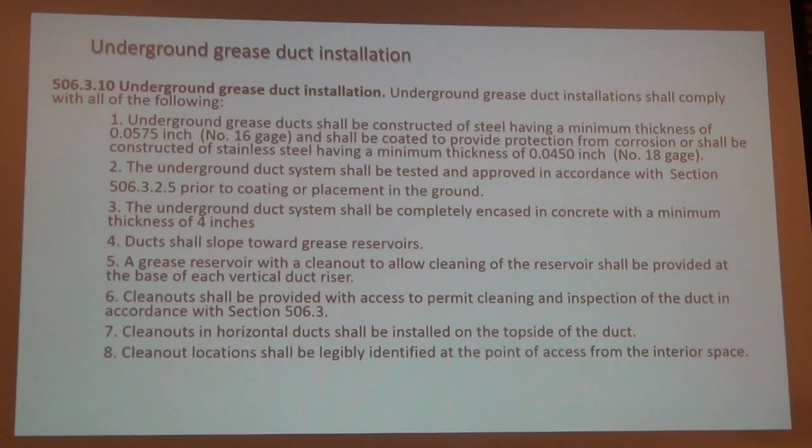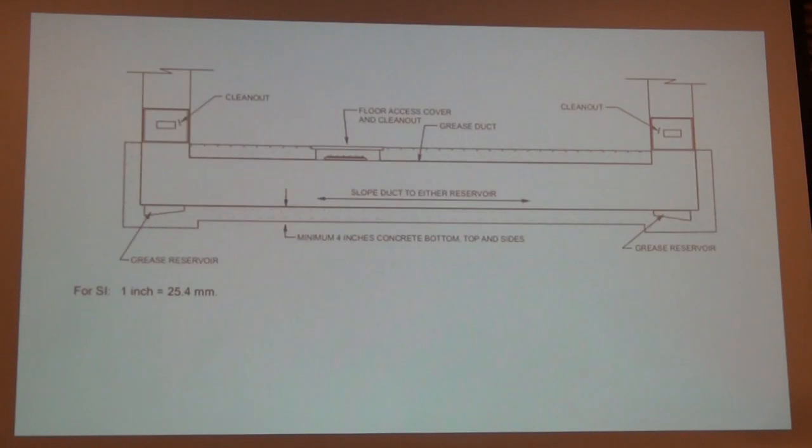And then if there are any cleanouts, they have to be on the top side of the duct. And then the cleanout locations shall be identified with access to an interior space. Here's an example showing that.